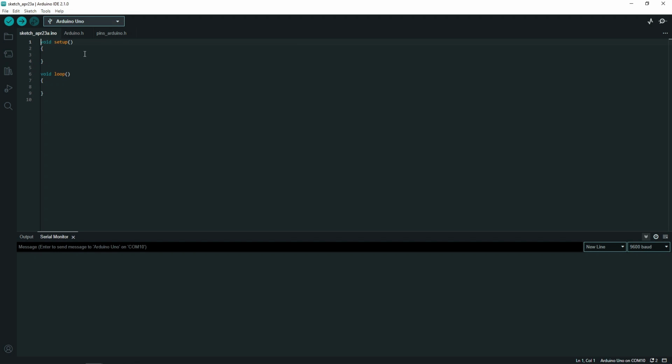And so if we go back to our Arduino IDE, what I'm going to define at the top is btn, button, as pin 2, and that will just make it easier to say which pin the button is on. So if we define the button pin as input, and like I said, you'll see a few options here, input and input pull-up. We want input pull-up.